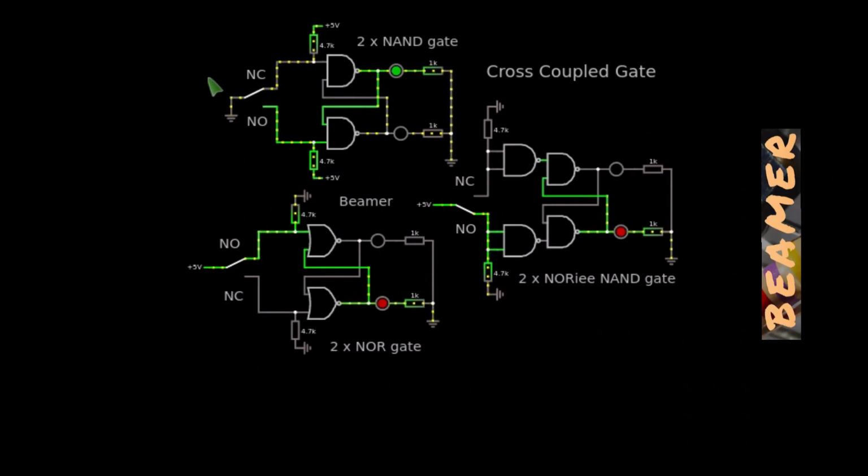Now, going back to the micro switch, and I will demonstrate this on the bench in a minute, but just to illustrate slightly, let's get back to the start position here, and let's just illustrate in a micro way how this actually functions. So as the micro switch is actuated, the contact wiper here lifts from the surface of this.